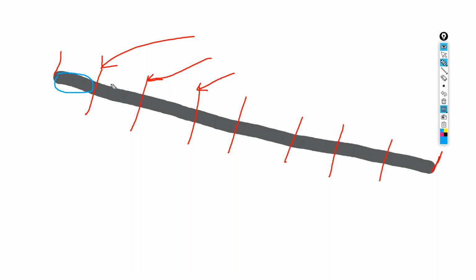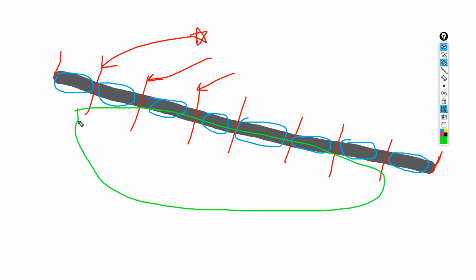And so a pipe section has a volume associated with it versus a computation station. This is simply a mathematical point where we are doing the calculations. And so here we have several computation stations and several pipe sections. So the reason why I bring this up is because when you're doing your water hammer analysis, there can be a lot of stuff that is happening at these interior pipe stations, and you're going to want to know what's going on inside the pipe.